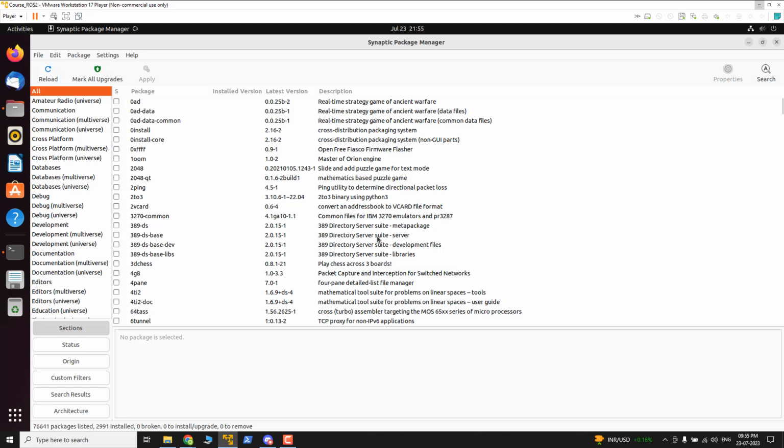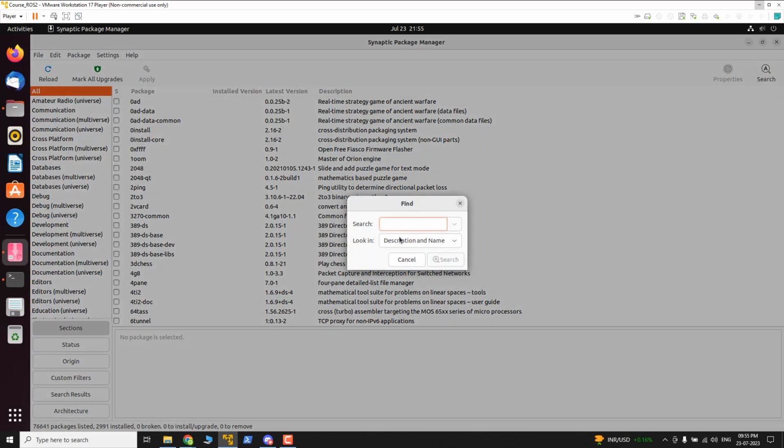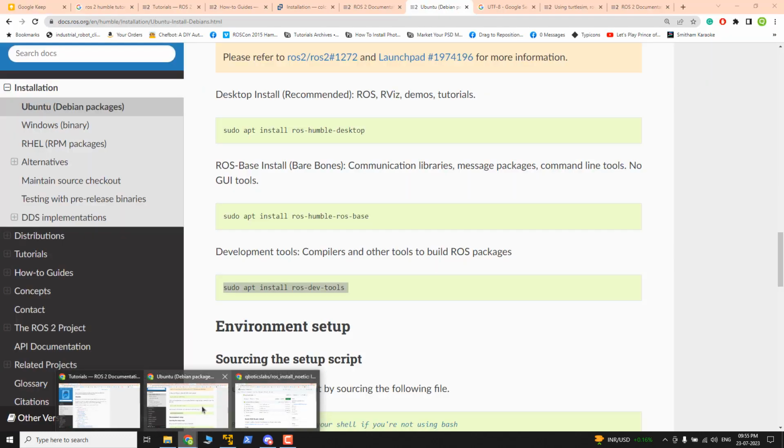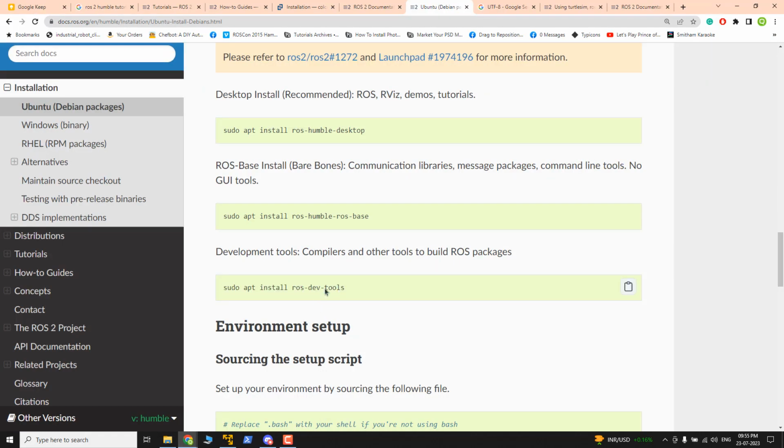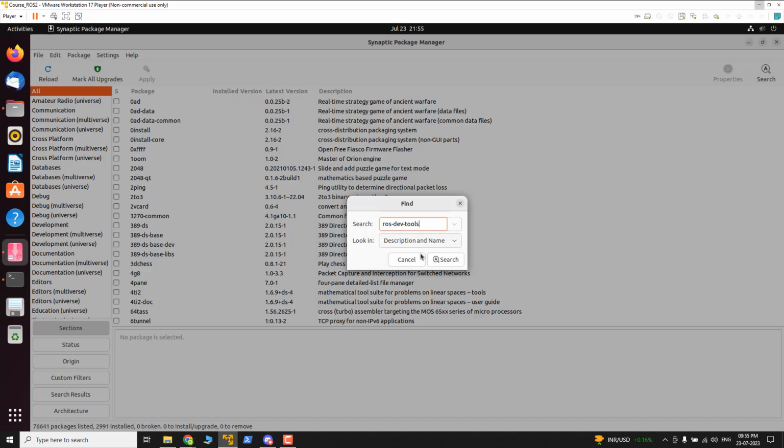In ROS 2, the build tool that we are using is Colcon, which is the latest build tool. And when we enter colcon, it will do the same stuff that catkin_make does. Okay, so let me check the ROS dev tools package. Let me double check whether it is installing Colcon.